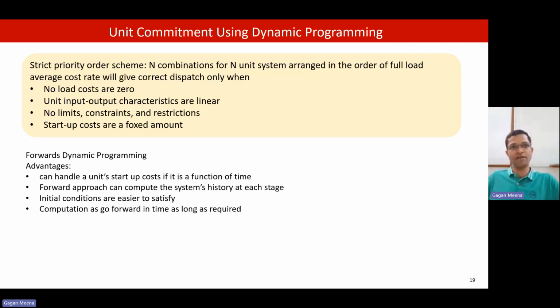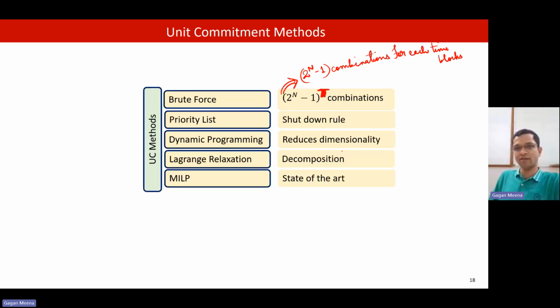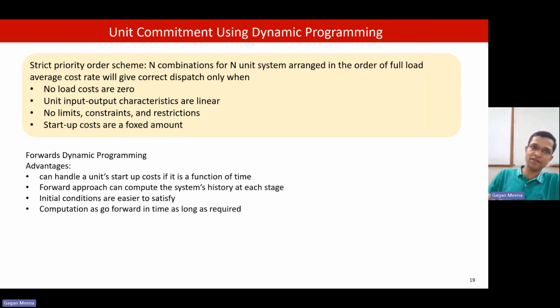This lets us move to the unit commitment using dynamic programming. Here, if we consider all these combinations, then dynamic programming also becomes computationally challenging. We have already seen that there are 15-minute time blocks, and we need to solve this unit commitment quickly. Here, we need a quick solution. We cannot wait for a day to solve the day-ahead unit commitment problem. That's why time is crucial here.